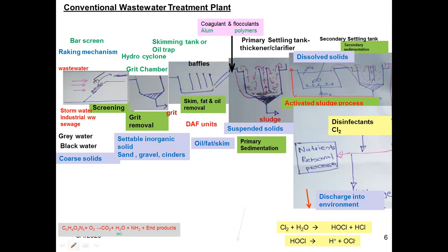These are the main things we have to care about. These two compounds, hypochlorous acid and hypochlorite ion, oxidize the pathogenic bacteria, pathogenic microorganisms and other constituents, so they do the disinfection.